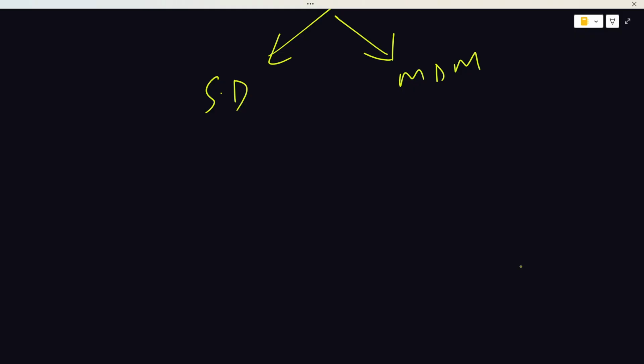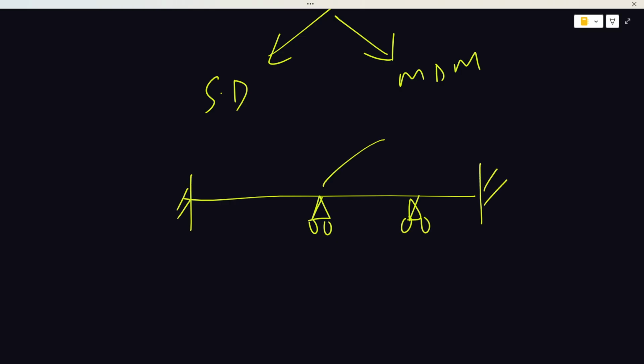Yeah. So it's an iterative process, unlike the slope deflection method, where we solve a lot of simultaneous equations. For instance, maybe we have a structure with two joints that are free to rotate. It means that we have two simultaneous equations in order to get the two displacements, which are the two rotations.